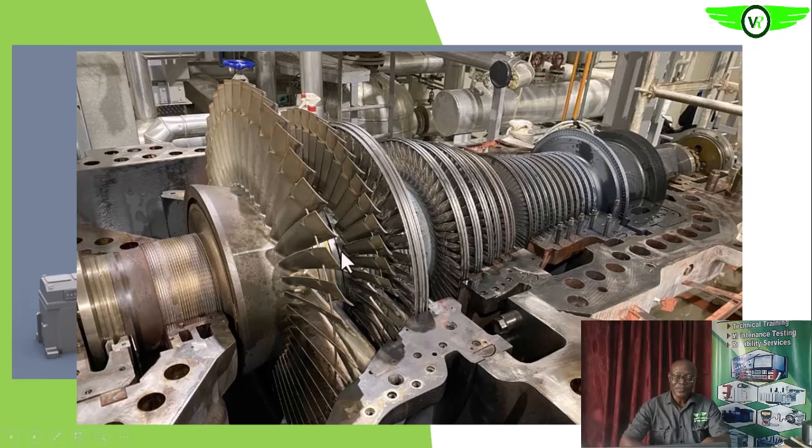So this is an opened up steam turbine. We have the stator, this is the rotor, and this is the blade on the rotor, or these are the blades on the rotor. Between these rotor blades, we have the stator blade. These are the stationary blades, so they are always in between. Then this is the labyrinth seal that we discussed the other time.